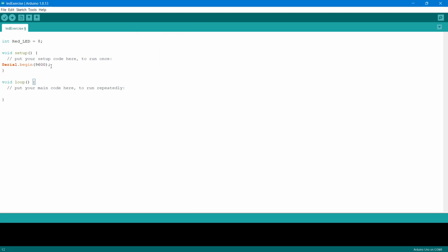And now we'll have to declare the pin mode. So the pin mode is going to be our red LED. So I can just copy this here. Sometimes it's best to copy the variable name because any typo mistake can render your code redundant, or it wouldn't work. Okay, I'll put a comma here.